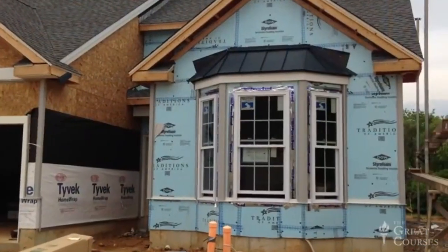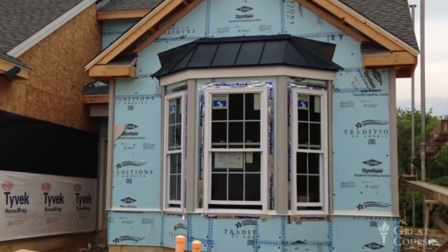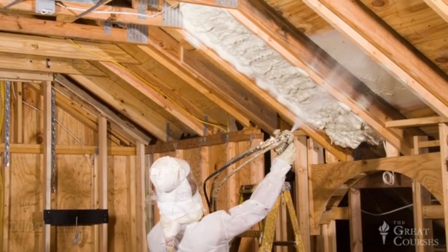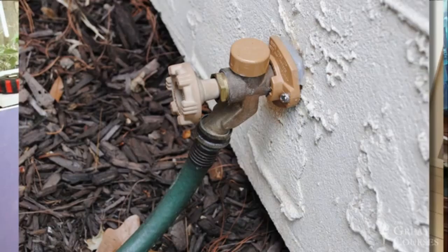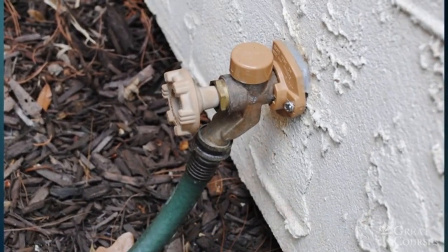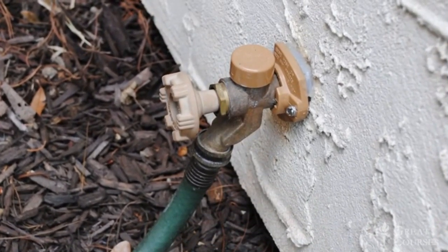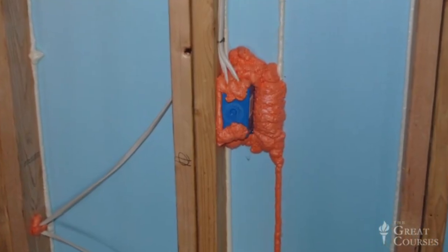First, the building envelope should include a well-defined air barrier, typically consisting of exterior house wrap or rigid foam insulation, interior spray foam insulation, or well-sealed interior drywall. Second, the inevitable penetrations through the air barrier, for example at vents and outdoor faucets, outlets, and light fixtures, must be thoroughly sealed with caulk or sealant.